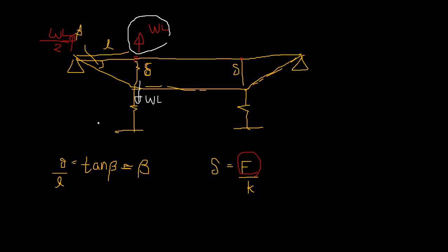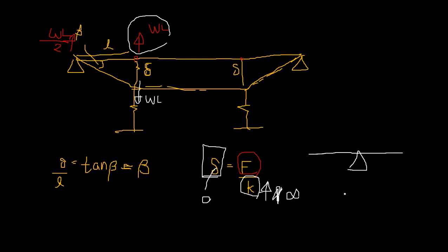deformation. But since the spring's stiffness is finite, it will have a relatively considerable displacement. What happens if your stiffness is infinite? This is going to infinity, so that your delta becomes almost 0, so that it will act as just a pin support, right? Where it doesn't show any displacement and it remains as it is due to infinite stiffness. So everything depends on the stiffness, right?